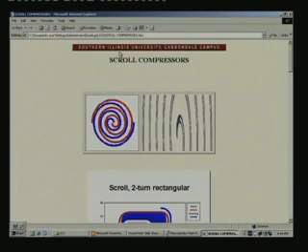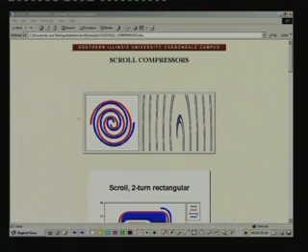Yeah, you can see this is downloaded from the internet, and it is made by the Southern Illinois University, and this picture here shows, for example, one spiral member and the other spiral member. One is fixed, the blue one is fixed, and the red one is orbiting. As it orbits, suction, compression and discharge takes place.